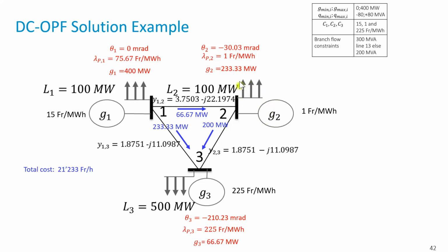So we find that when the line constraints are as we said here, the most saturated generator is generator 1, and power is flowing from 1 to 2 and from 2 to 3. And the line that is saturated is line 2, 3. We see that here with the capacity, and that is full. The marginal costs will be slightly different, but they will not be very different from what we had before.